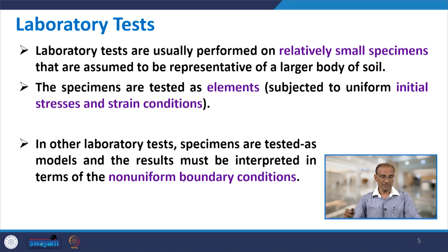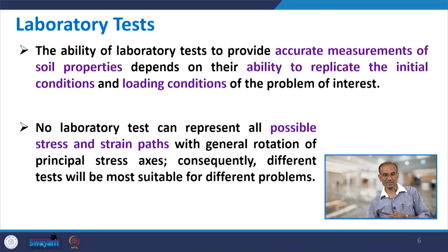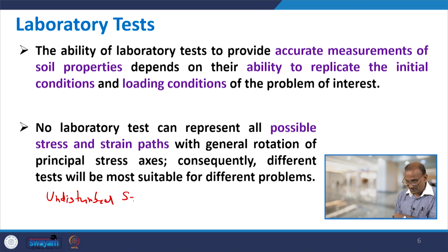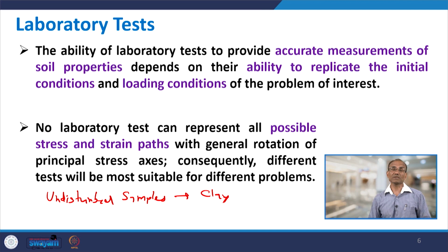It is easy to get undisturbed samples in the case of clay or cohesionless soil, but it is difficult to get undisturbed samples in sand. As a result, laboratory tests are more recommended for clay soil, but in general, as we discussed, one should conduct both field test as well as lab test. Field test is important and lab test is also important.